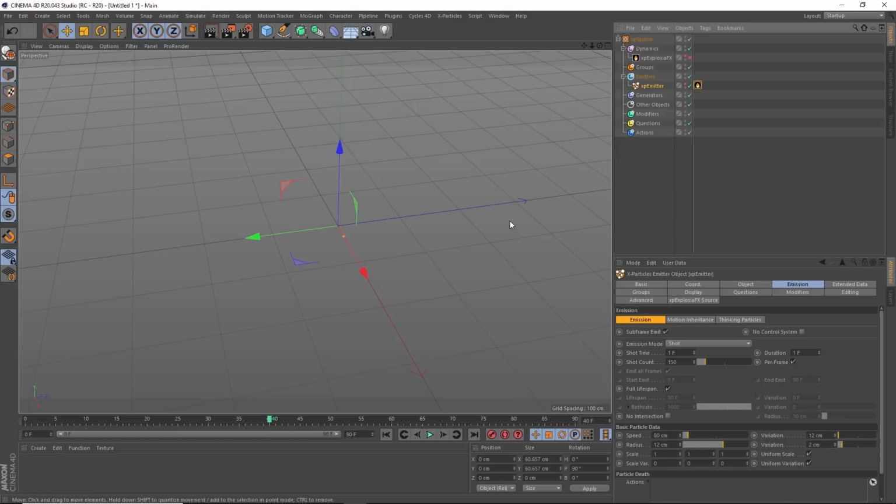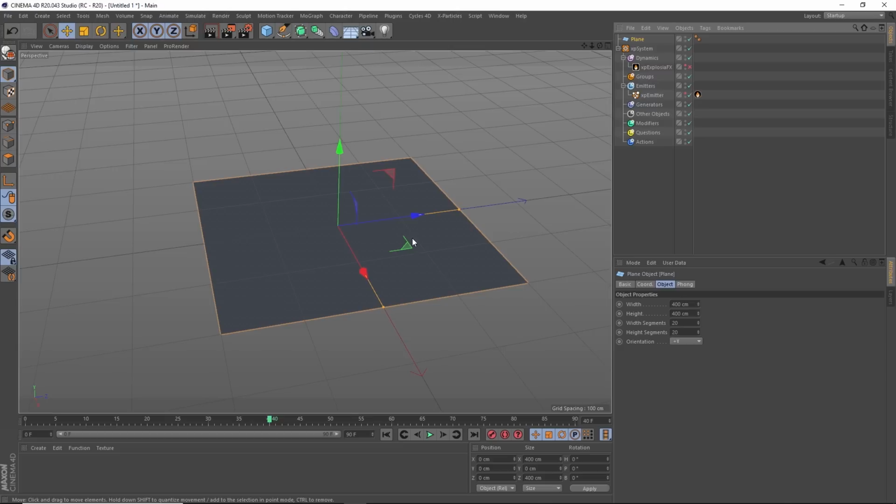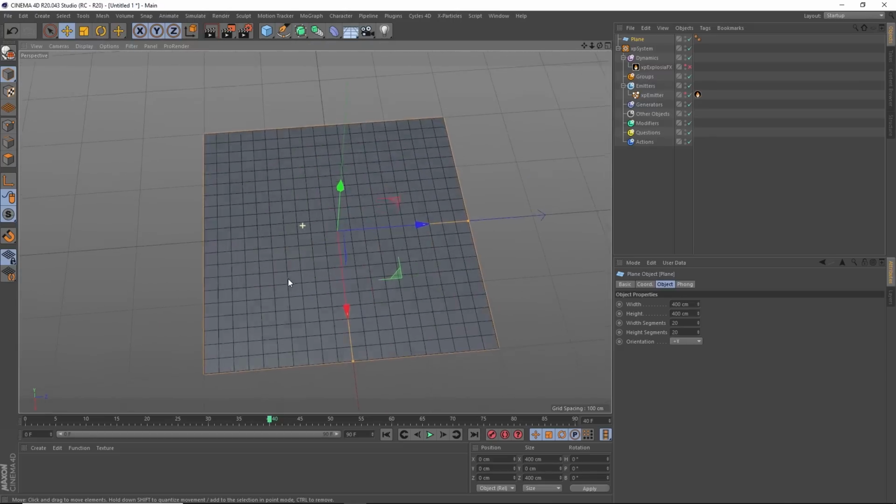So now what we want to do is create our particles, which are going to have their orientation advected by that shockwave. So we want them to be static, and we're going to make them static by sticking them to a bit of geometry. So let's bring in a plane. That's going to be our geometry. And I'm going to hit N D to display those lines.